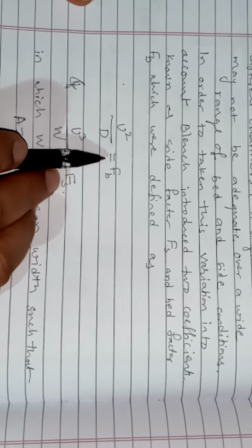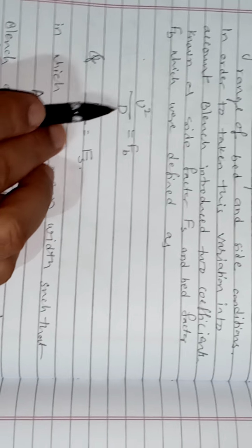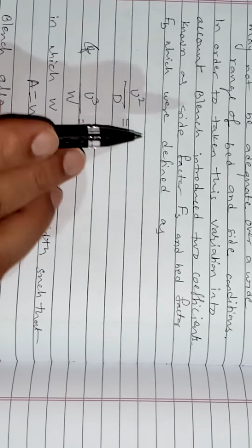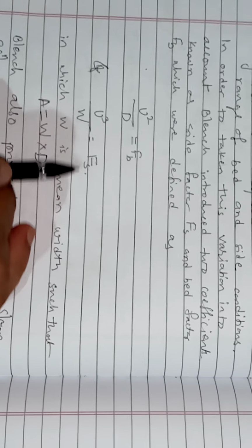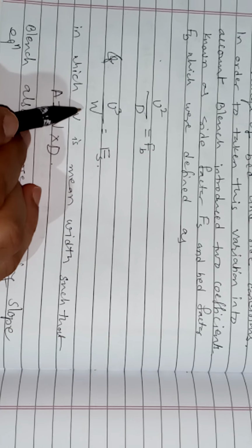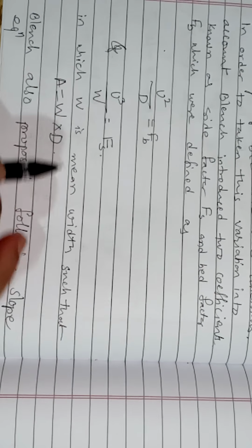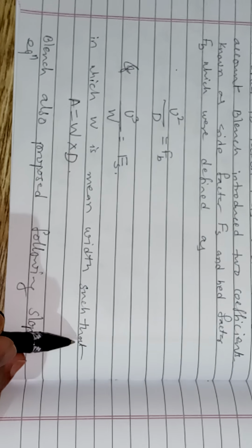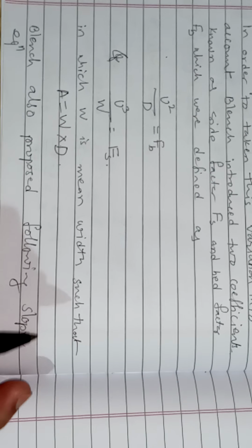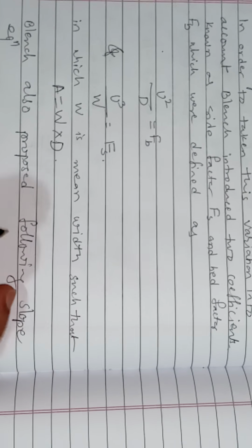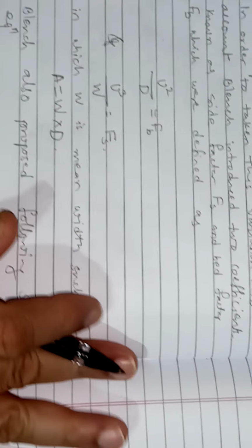So Fb = U square / D, where U is the mean velocity of the flow and D is the depth of the flow. And Fs is defined as U cube / W, in which W is the mean width, so that A will be equal to W D. Blench also proposed the following slope equation,